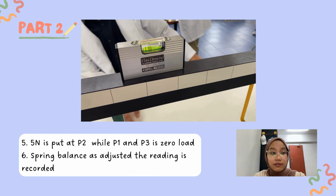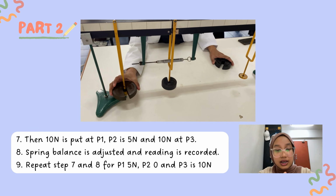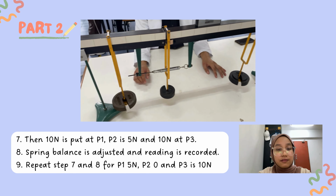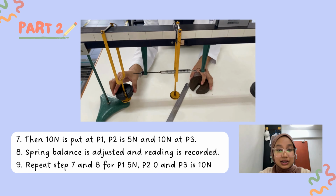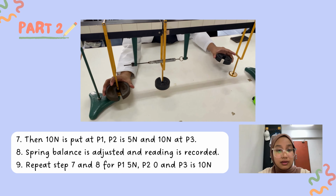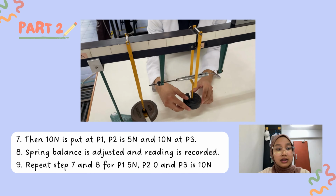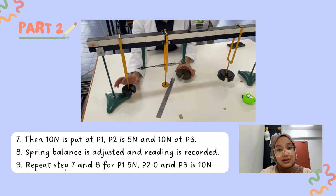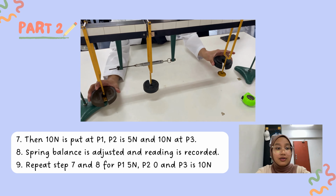After that, we repeat the experiment using 10 Newton. We put 10 Newton at P1, 5 Newton at P2, and 10 Newton at P3. Then we adjust the spring balance and record the data. After that, we repeat the experiment for the other reading, which is 5 Newton at P1, 0 Newton at P2, and 10 Newton at P3, and record the data. So that is done for part 2.